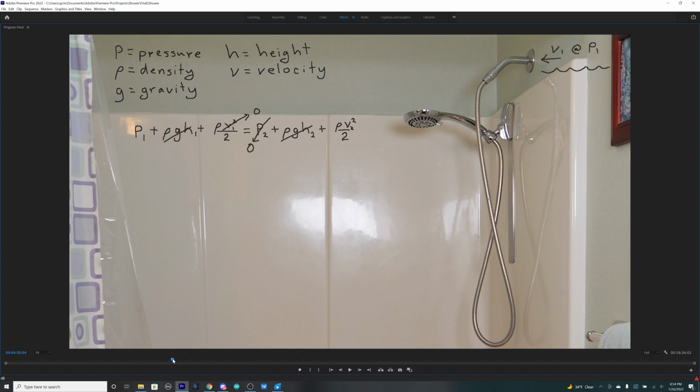But if we're considering this like an above ground swimming pool that we drilled a hole in the side, the velocity inside the swimming pool is nothing. It's just sitting there. It's ginormous. You consider it infinite. So inside the swimming pool, there is no velocity. So the V1 goes to zero. And because it's zero, this whole term just disappears.